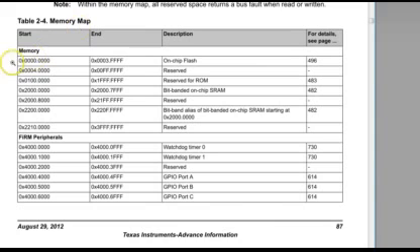address space. I hope you recognize the first island on this map, called on-chip flash, from address 0 to 3FFFF, which corresponds to 256 kilobytes of flash memory. You should also recognize the familiar RAM island, starting at 2 hex followed by all zeros, which is named here bit-banded on-chip SRAM, whereas SRAM stands for static RAM.